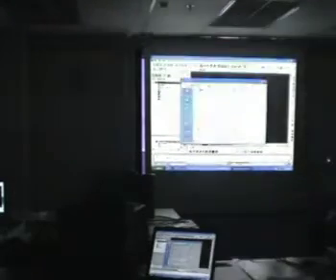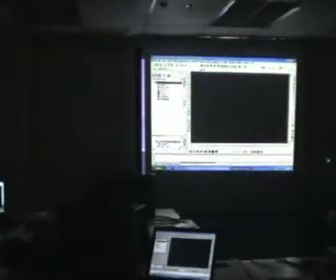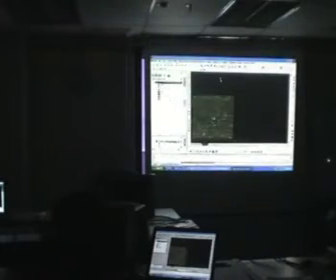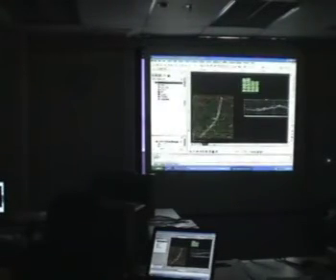Instead of starting from scratch, I'll open up a drawing which I already have, just to show you the major difference. The bit about converting 2D to 3D can also be done in Civil 3D using the same methods, because actually Civil 3D comes together with Map. So you can see the workspace at the bottom here. You can use that to convert 2D to 3D as per the Land Desktop method I showed you just now.